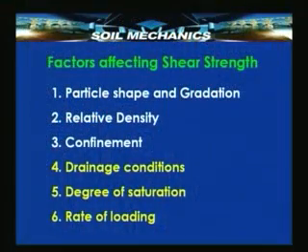These are all parameters which are particularly important from point of view of shear strength of cohesionless soils. On the other hand, for cohesive soils, what are more important, obviously because of their low permeability, are drainage conditions, degree of saturation, rate of loading. In addition to this, there is another important parameter which during the course of today's lecture we will pay some attention to, that is the stress history, the history which shows what kind of stress the soil has undergone in the past. This is particularly important for clayey soils.